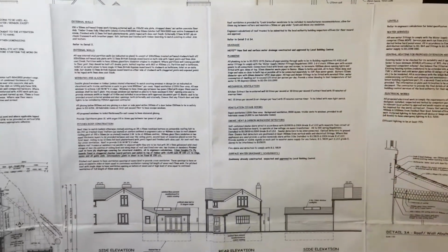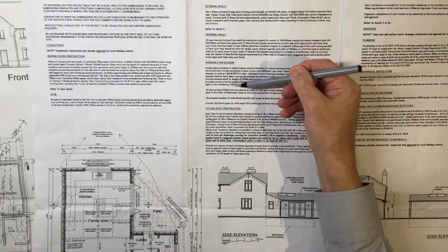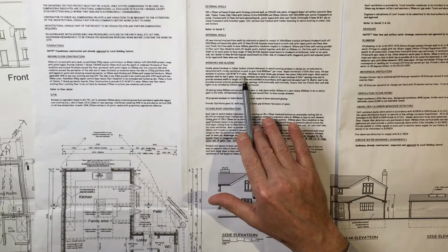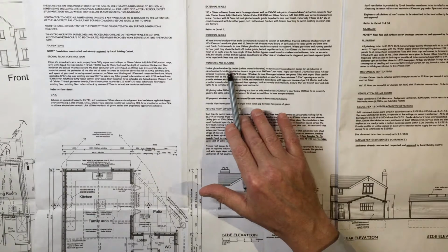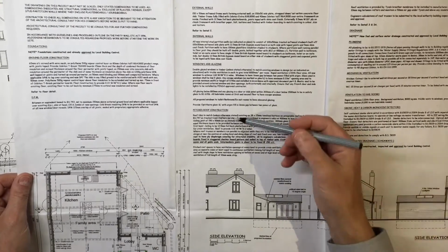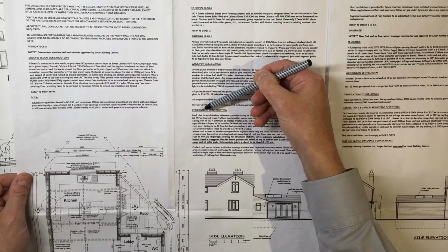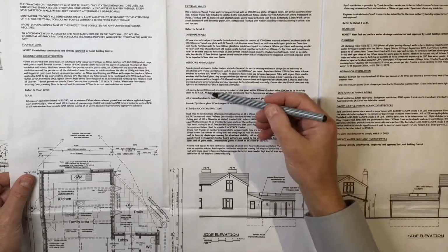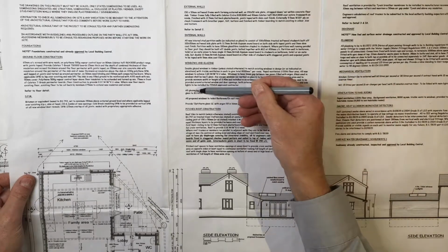They will vary from project to project, and you can see the construction notes are really quite detailed, and they have to be. Yes, it even gives you an indication of the U values that the window must achieve, the amount of heat loss from a window, the maximum amount that it must allow through, if you like. Okay. And this one specifies the information for the pitched roof. There's the pitch, the gable end, and quite a lot of detail, even the British Standard number in relation to the glazing.